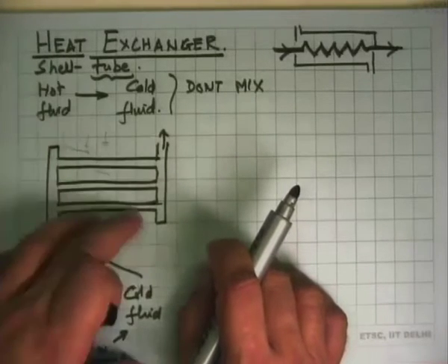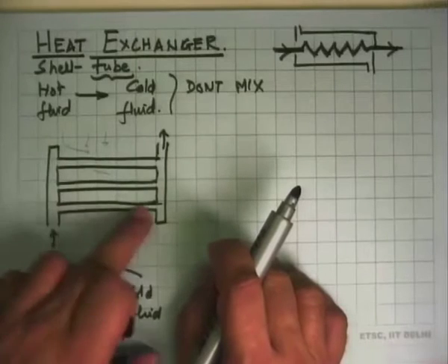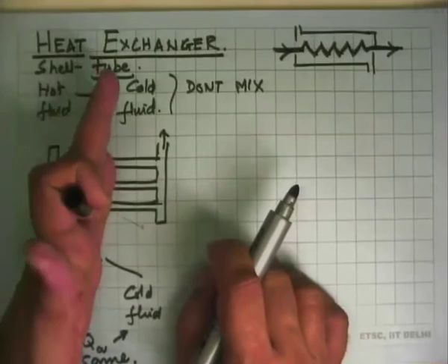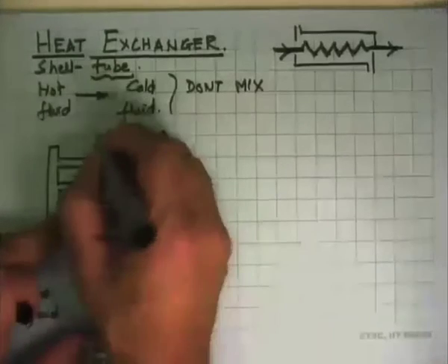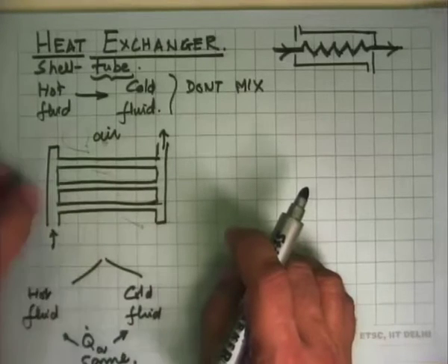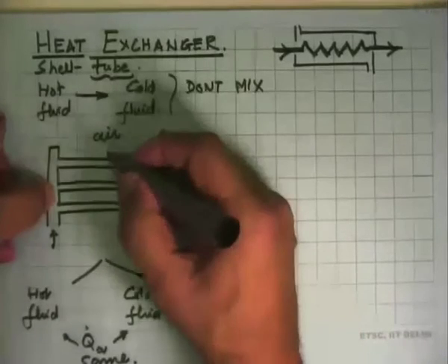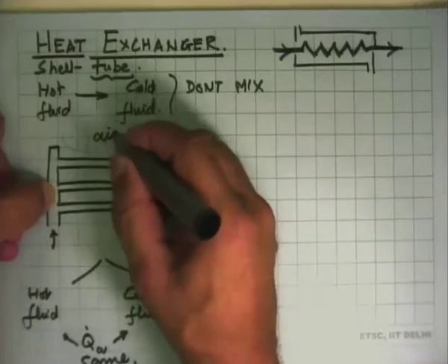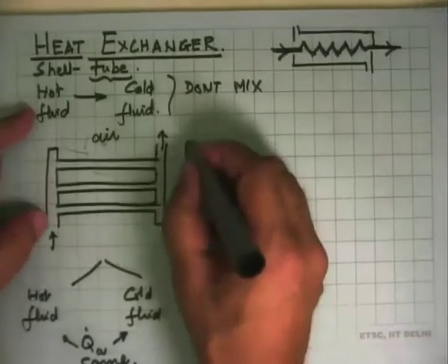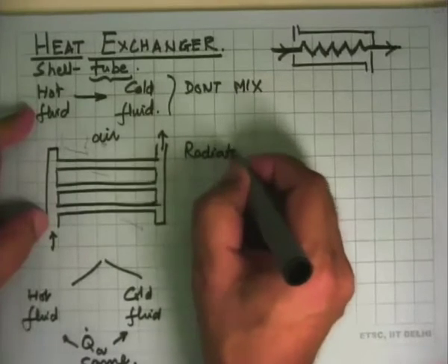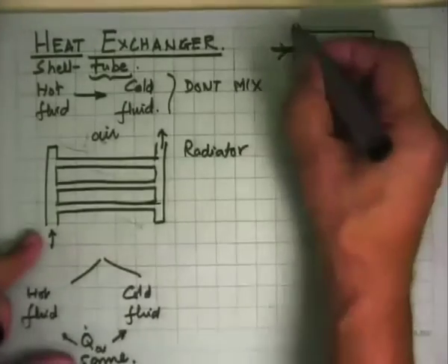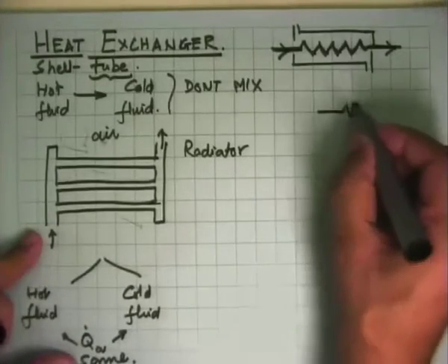And that whole device is basically that the hot water is flowing inside this, becoming cold, and outside this we are blowing the cold fluid, which in the case of a radiator is ambient air. So that air goes over it, and as long as the temperature of the coolant inside is more than the air temperature, it will give heat to the air, cool down, and the cold fluid will go out there. So that's a very common example of a heat exchanger. The difference is that we do not have this outside thing shown there, so we can just show it like this.